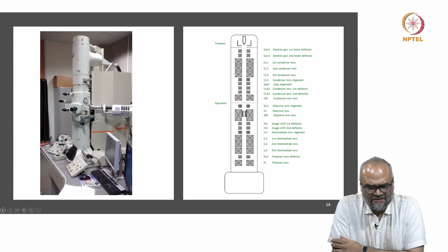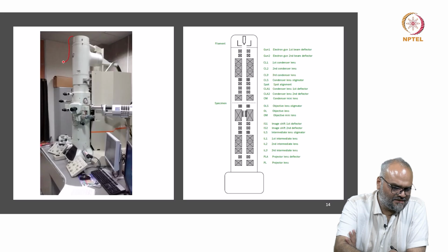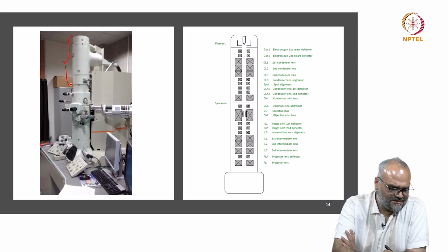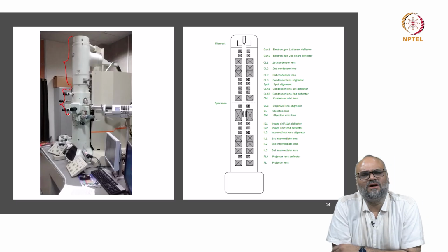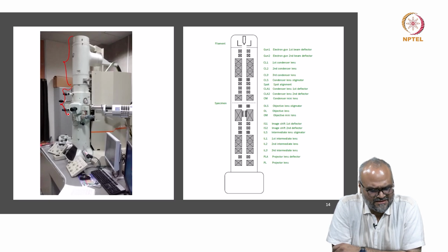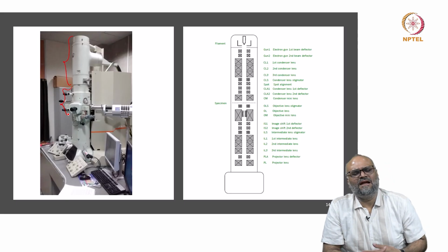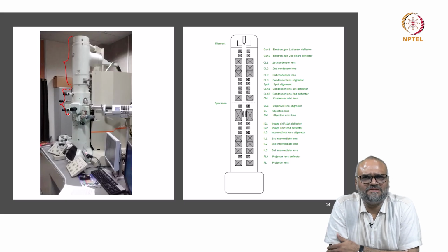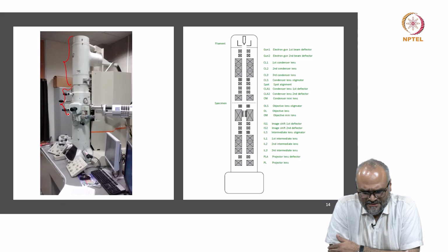Till now, we've seen a few components of the microscope. We've seen the types of electron sources, the construction of sources. We've seen the lenses or the imaging system that is used in the microscope, construction of lenses, kinds of lenses, deflector coils, and so on. We've drawn some analogies with basic wave optics on trying to understand how a lens functions, what is happening at the object plane and the backfocal plane, and how you switch from a real space to reciprocal space or from spatial domain to frequency domain.